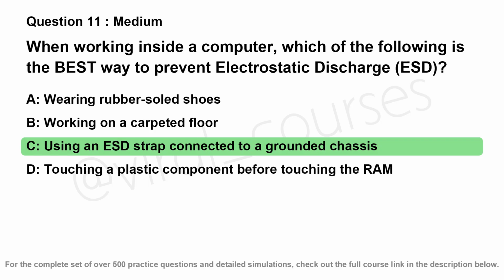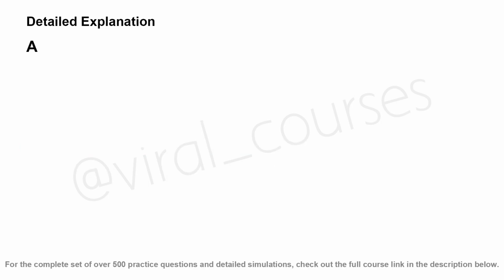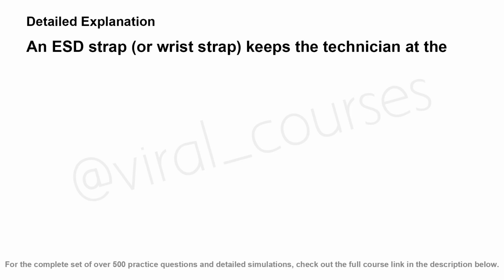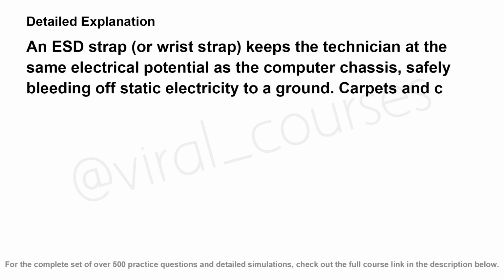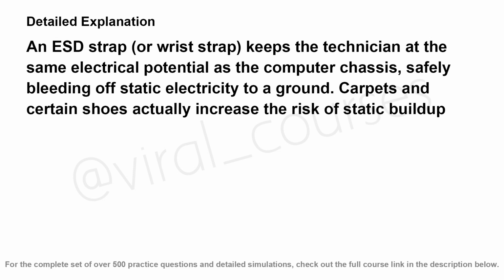The correct answer is C. An ESD strap, or wrist strap, keeps the technician at the same electrical potential as the computer chassis, safely bleeding off static electricity to a ground. Carpets and certain shoes actually increase the risk of static buildup.